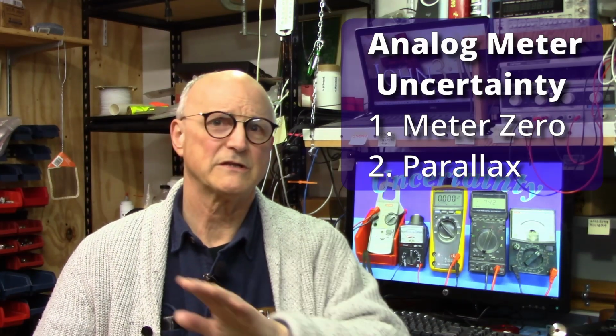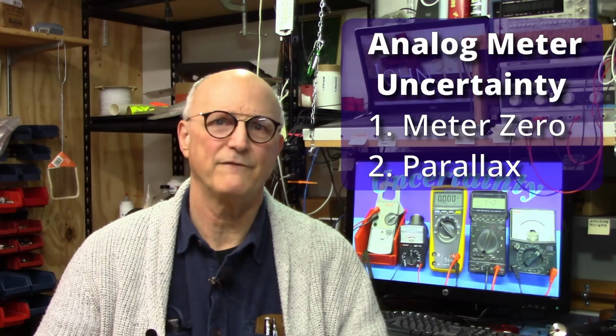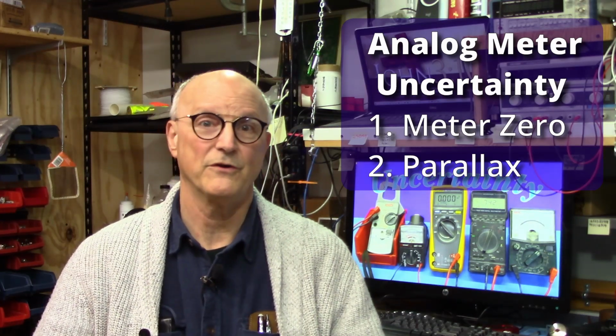Now, I go over this whole business of accuracy reading an analog meter movement in my video on this subject. I put a link to that video up in the corner for you. The point here is that even if we do everything right, the best we can get in a measurement is within 3% of the full scale reading for any scale. On the 500 volt scale, this would be plus or minus 15 volts.